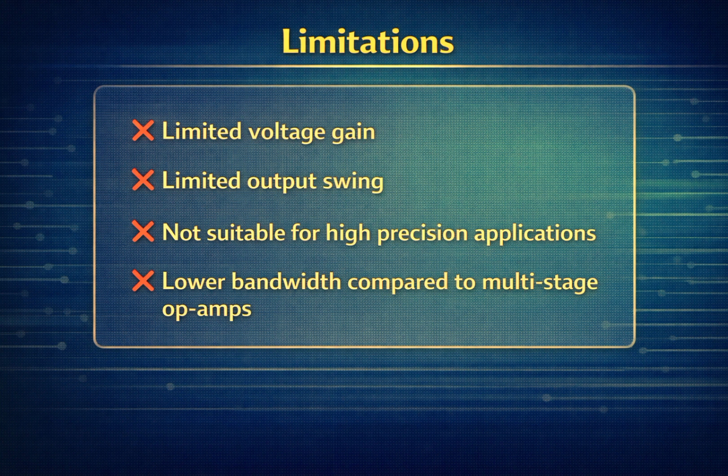Limitations. But every circuit has limitations. Limited voltage gain. Limited output swing. Not suitable for high-precision applications. Lower bandwidth compared to multi-stage op-amps. Since it has only one stage, it cannot provide very high gain. For high-performance systems, multi-stage op-amps are used.